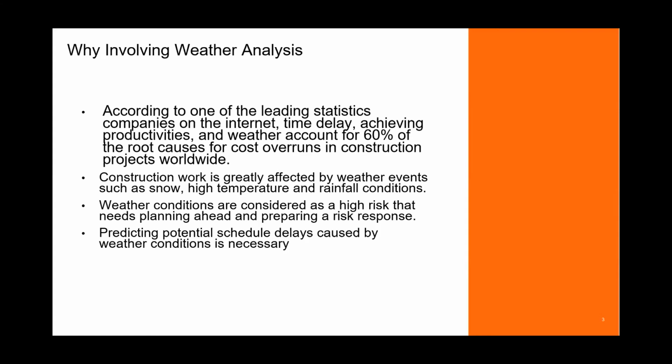So you also can't build a schedule based on 0% weather. There are other ways of accounting for weather delays in schedules, though some are rarely used. I just want to mention this one, not to use it, as it's a bad practice: prolonging activity durations in the schedule for some activities.